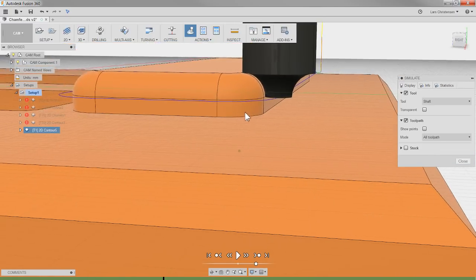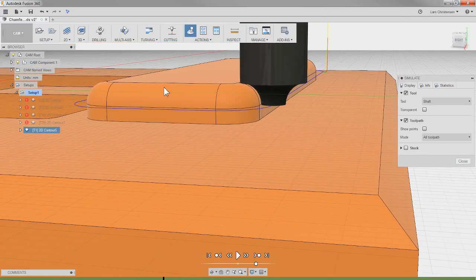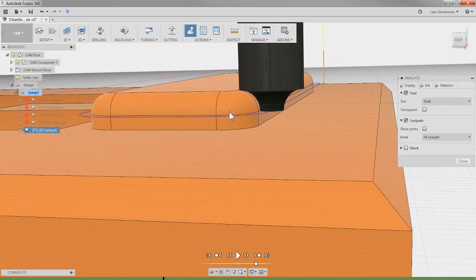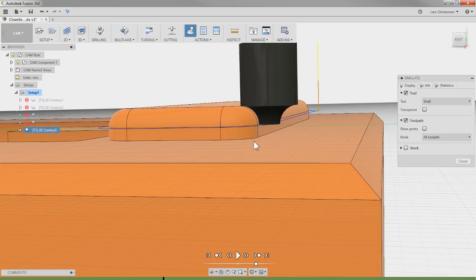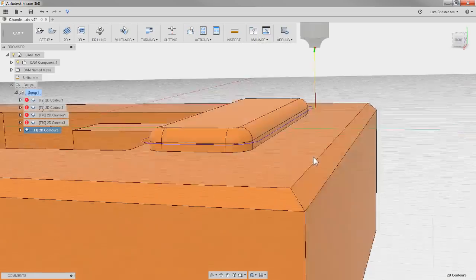Again, when it comes to radius cutters, I would actually walk them in. So I would run a test cut where maybe I have it backed off in my cutter compensation on the control a little bit, so I can kind of play with it at the machine, because this can really, I mean, just a tiny little bit and your part's going to look like you screwed it up when you're maybe only down half a human hair or something like that.